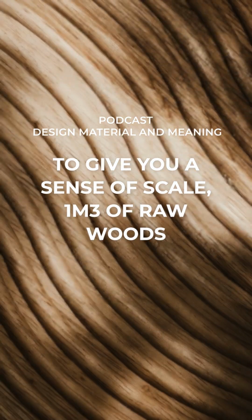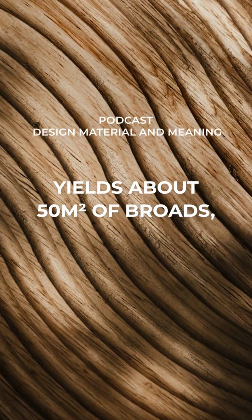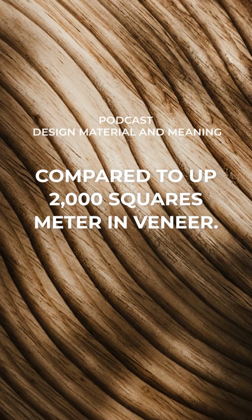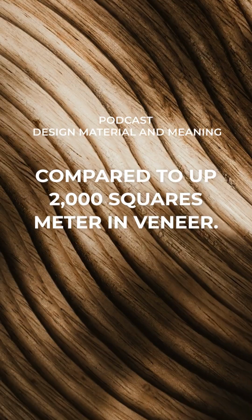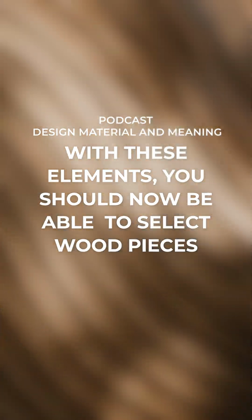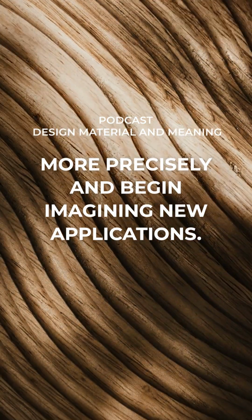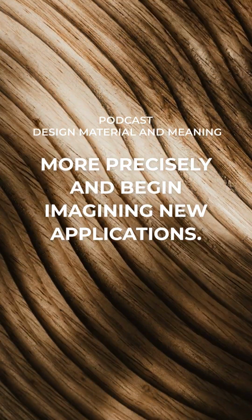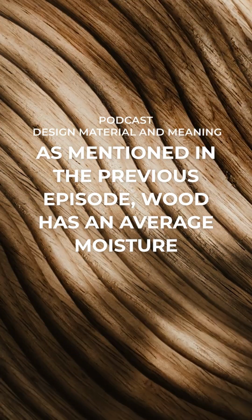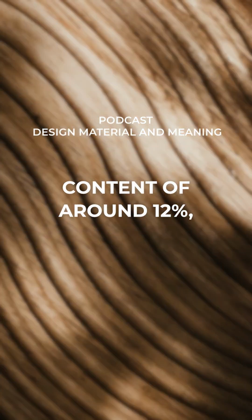To give you a sense of scale, 1 cubic meter of raw wood yields about 50 square meters of boards, compared to up to 2,000 square meters in veneer. You choose the technique. With these elements, you should now be able to select wood pieces more precisely and begin imagining new applications. As mentioned in the previous episode, wood has an average moisture content of around 12%.